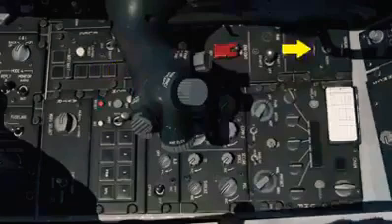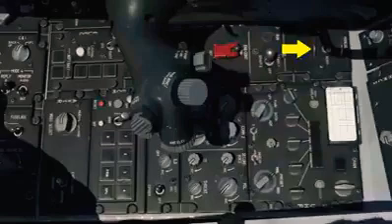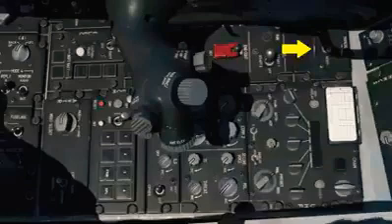In case of a deep stall departure, the pitch override switch allows you to command greater authority from the stabs to help to get the nose pointed downhill so you can gain speed for control flight. The guards on either side of the switch allow the pilot to better grip it in case of inverted departure when he's hanging upside down by the straps.